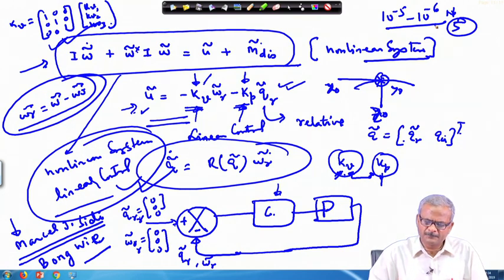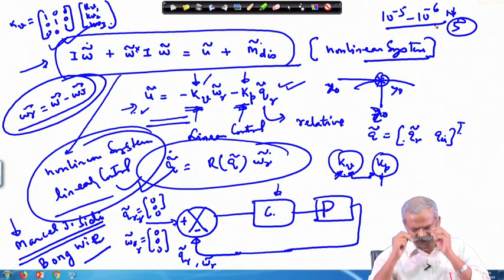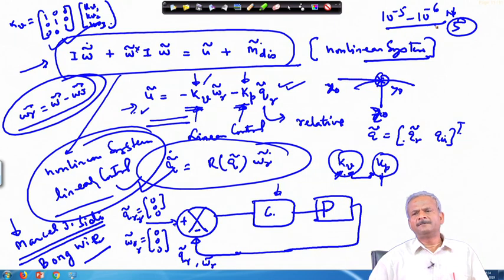Again it will be only the more mathematical proof involved. Okay, if you are doing it with the linear system, there is not much to do in that case, because you only need to place the poles according to your requirement, and in that case you have the LTI tool available in MATLAB, the linear time invariant system toolbox. That toolbox you can use to place the poles of the system, and you can get the desired result.